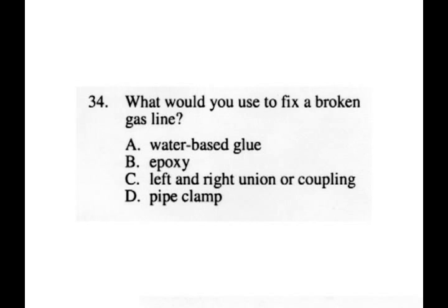Number 34. What would you use to fix a broken gas line? The answer is letter C, left and right union or coupling. The other 3 choices are an attempt to patch the line, which is absolutely forbidden.